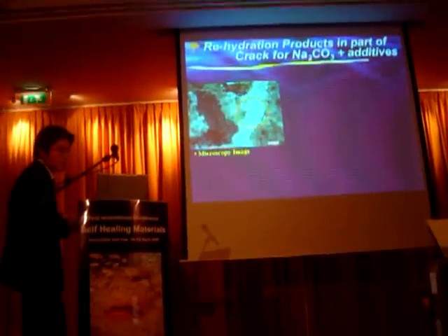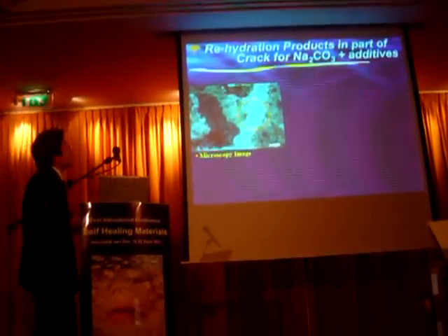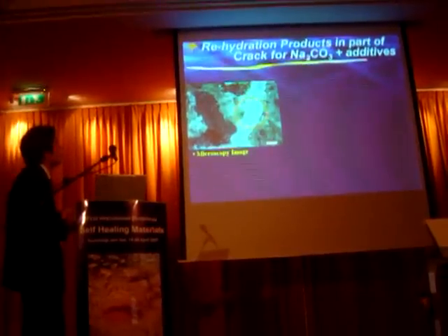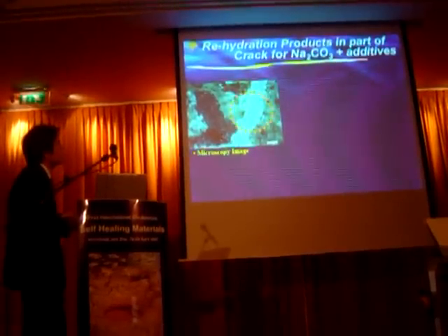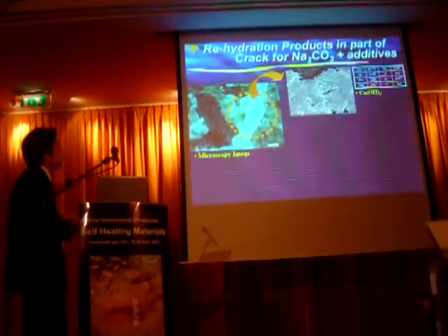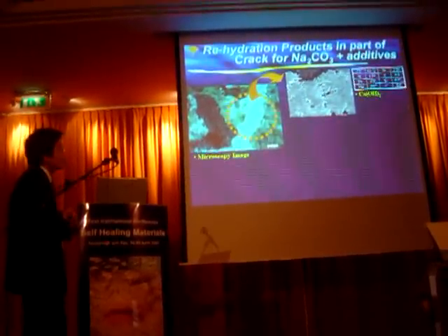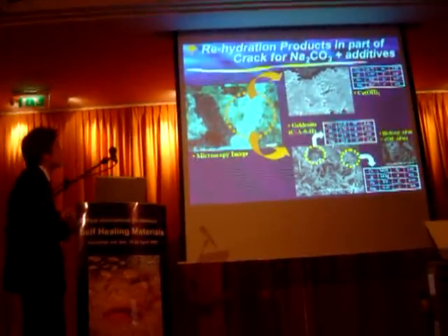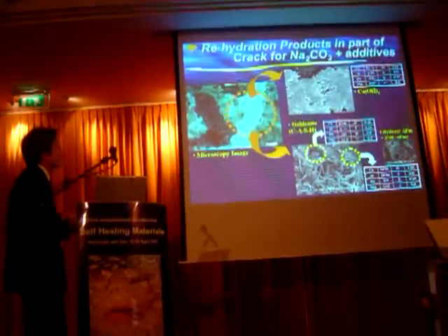And especially in the case of sodium carbonate and some additives, it shows the best performance of self-healing abilities in this research. And the same EDS analysis result revealed that the rehydration product was composed of products such as calcium hydroxide and hydrocalumite, calcium aluminum silicate hydroxide, and hydroxy AFm.